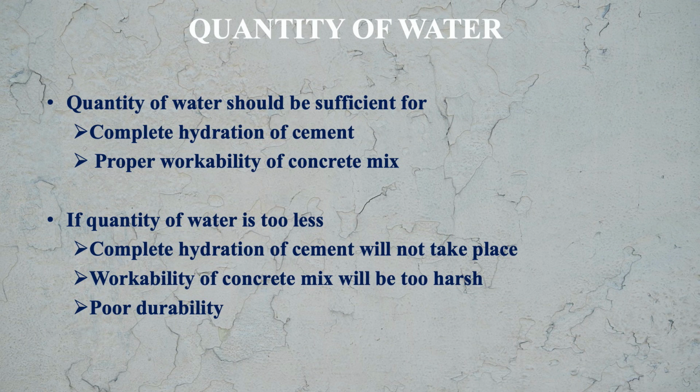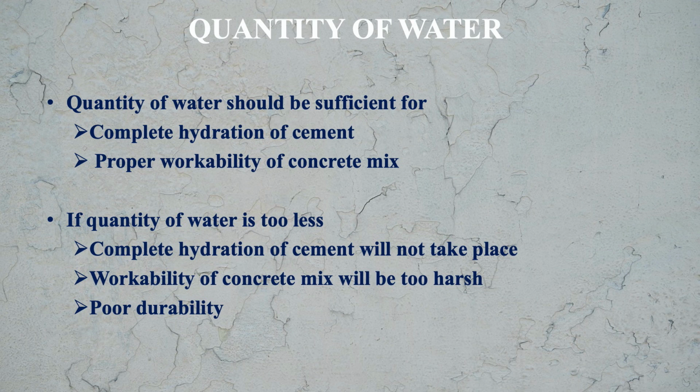Second, workability of concrete mix will be too harsh because water acts as a lubricant. So when less amount of water is there, our mix will not be workable. It will be too harsh. Third is durability. If sufficient quantity of water is not there in the concrete, then the concrete produced will not be durable.